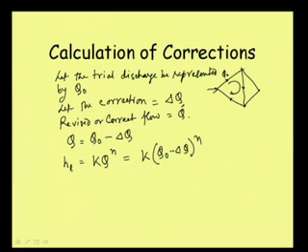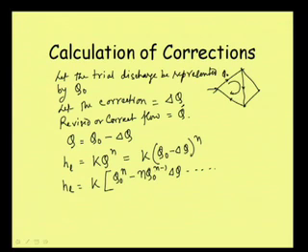Now, if we expand this in a binomial series, then we can write this, say HL, let us expand this in the form that is equal to K, then we can write Q0 to the power n minus n Q0 to the power n minus 1, then delta Q, and then of course we can keep on writing terms here. In the next term, it will be n minus 2 and this will be delta Q square. Then after that it will be delta Q cube.